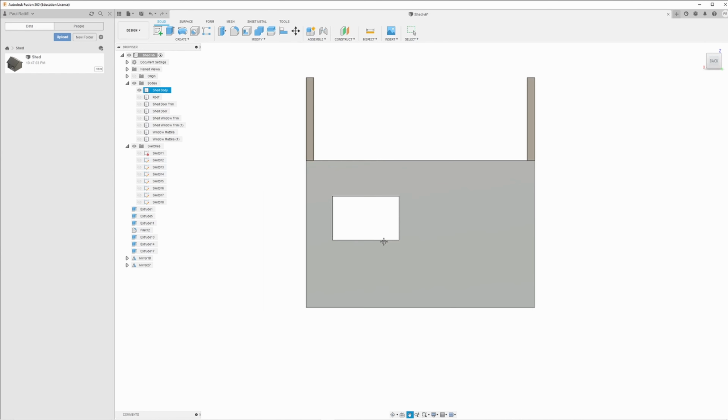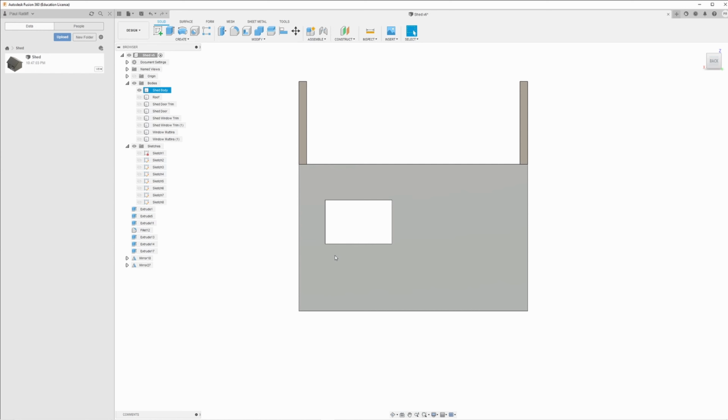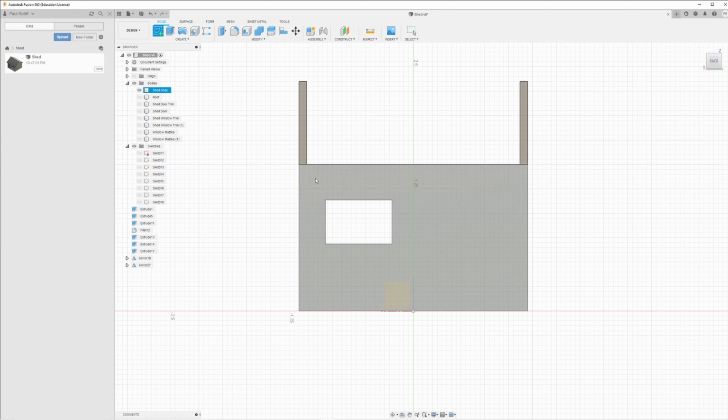And I have decided that I'm going to create my indentations for the beadboard 2 millimeters wide, which is approximately 6 to 7 scale inches in N scale. Actually, I should tell you what we're doing. We're not actually putting boards on these walls. What we are going to be doing is creating indentations into these walls to emulate the look of a beadboard. So as always, we are going to start with create a sketch,